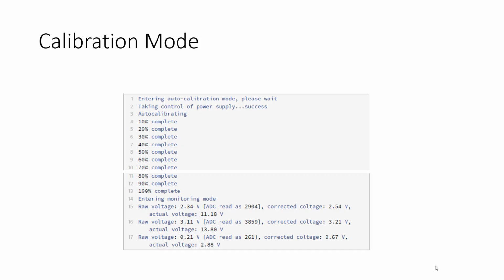Yeah, we have the cables in the box. Basically we have cables where one end is a banana clip you plug into the power supply, and the other end is an alligator clip that you're going to just clip on. But make sure you clip it on the one that says VBAT. VBAT is the high voltage one. The other one, of course, is just 5 volts. You've got it labeled 5 volts and you've got it labeled VBAT.